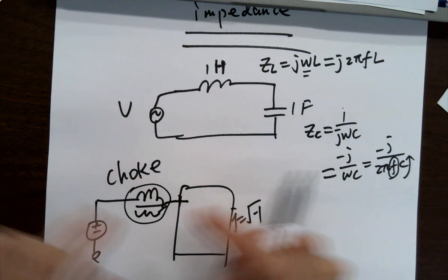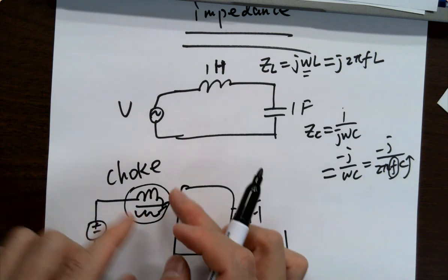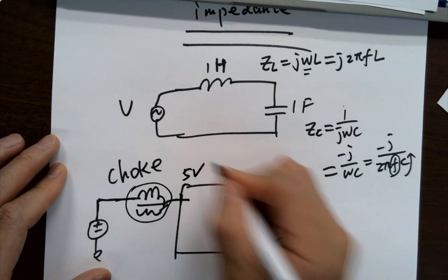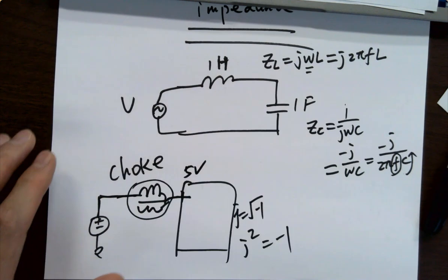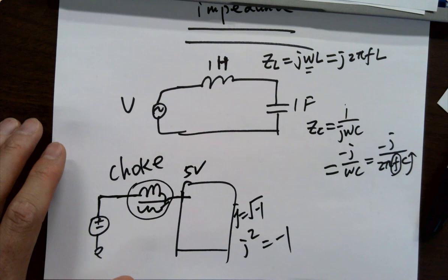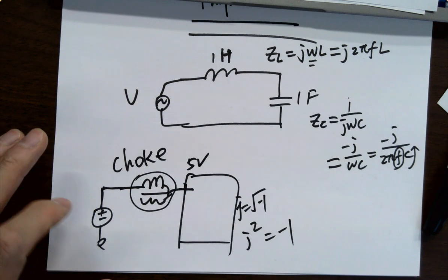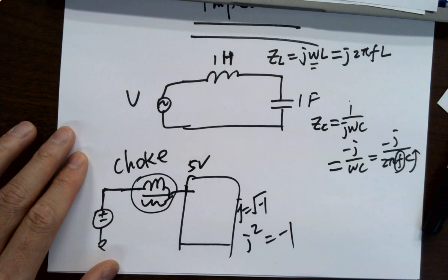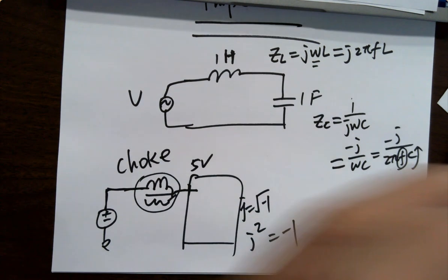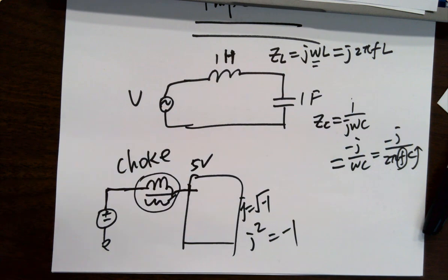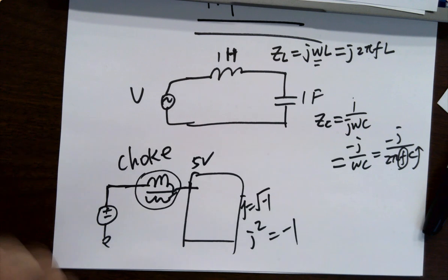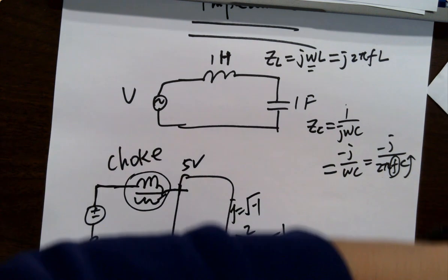Whenever you have a lot of AC noise, high frequency noise, it's able to block it, so only the DC part goes through. So you are getting a very stable 5 volts power supply for the microcontroller. It's more resistant to AC noise because it's rejecting AC, like a choke. It's choking. No AC is allowed, only DC passes. Makes sense?